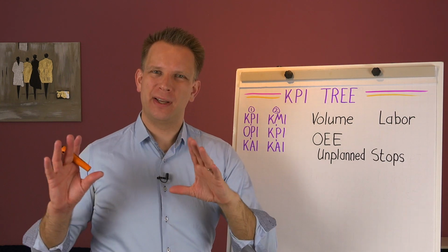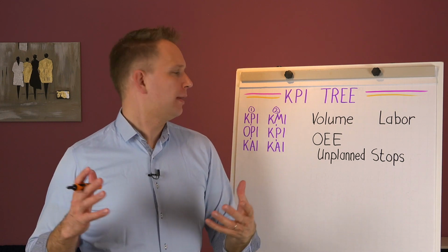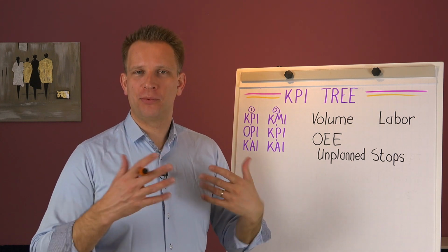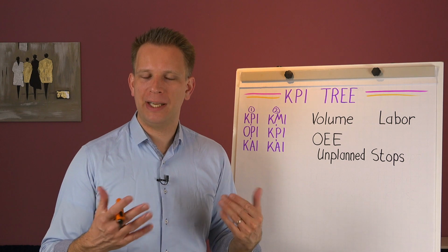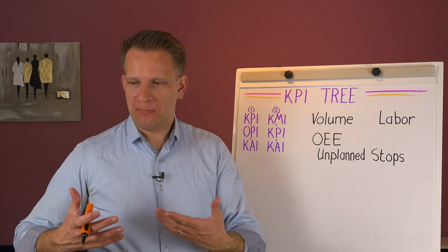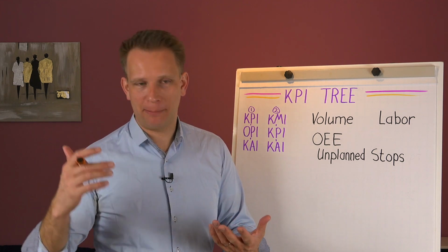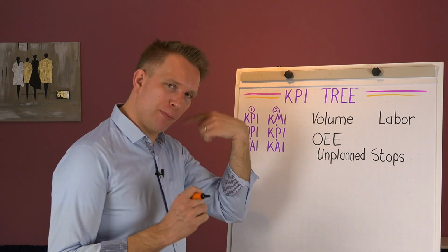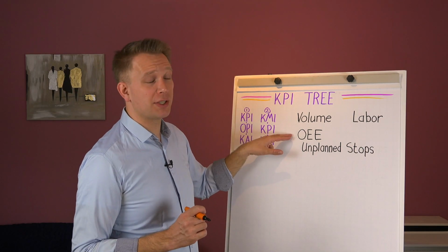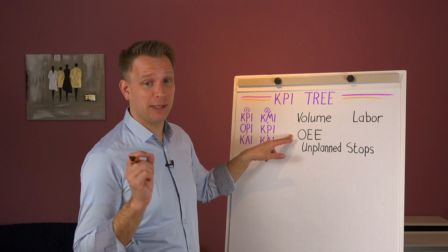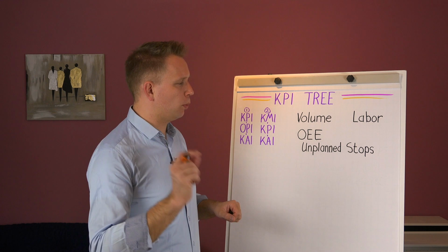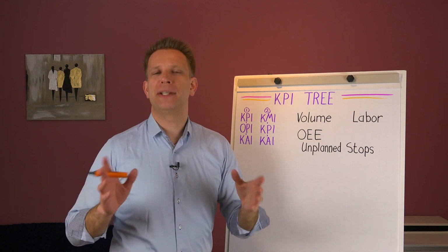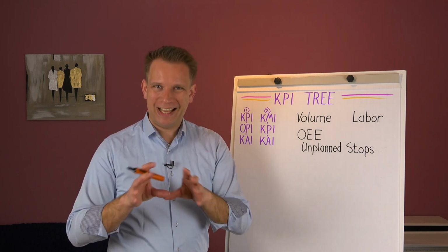They know that OEE is quite a wide type of indicator. It has a lot in it. So the influenceability by the production team is sometimes a bit difficult, right? In the end, you control OEE, of course, in all of the aspects, how you plan, how you do plant maintenance, how many breakdowns, things like that. But can we focus a bit more? They also make a translation and they say, we are interested in total OEE of at least our main lines, but we want our factories to specifically focus on unplanned stops, which means short stops, breakdowns, that part, right?